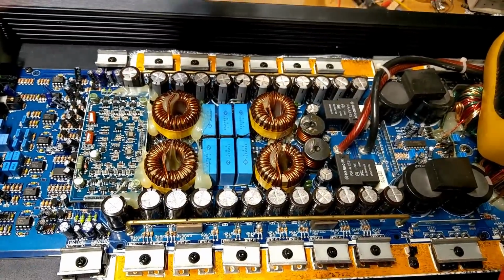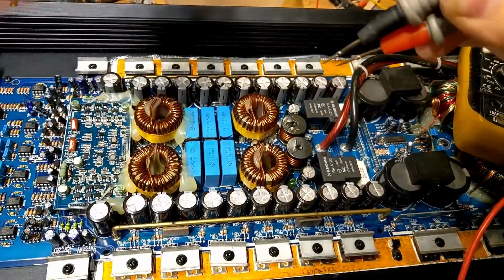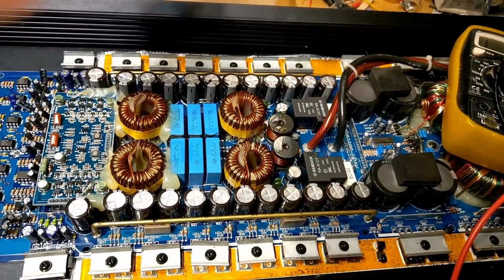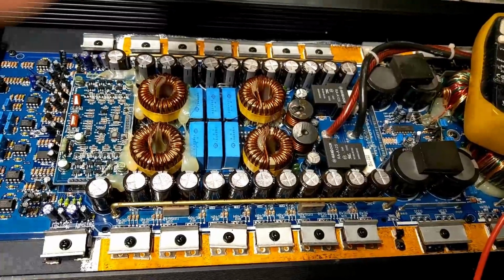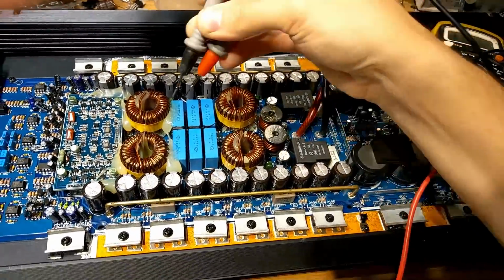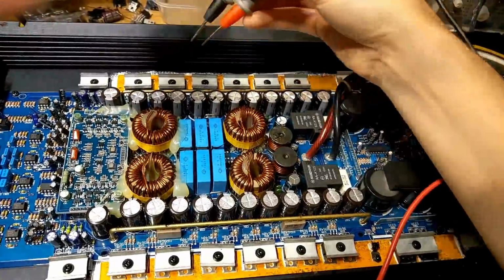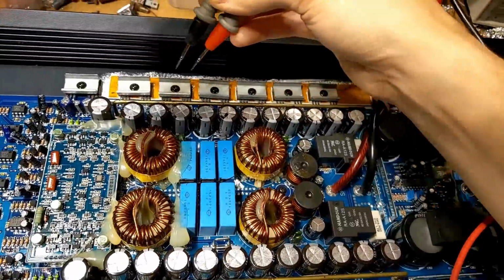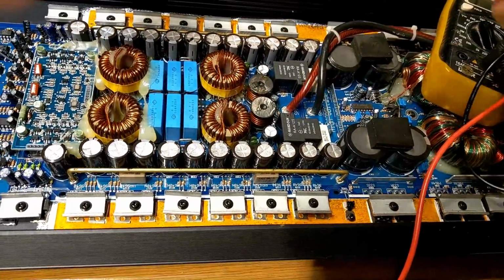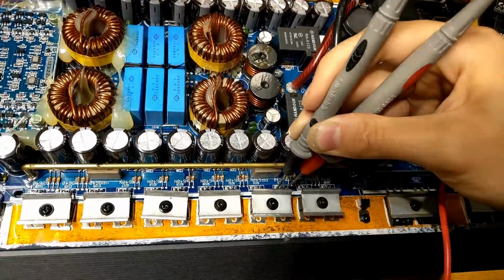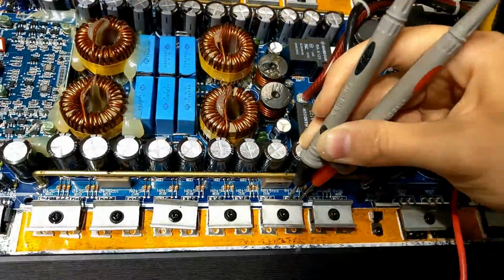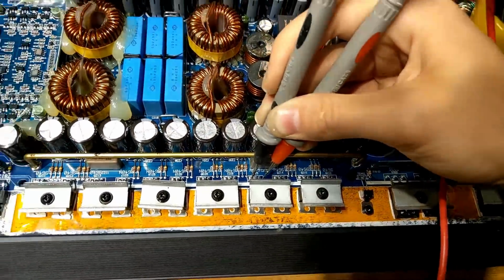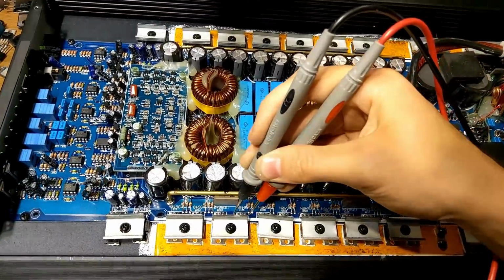So this amplifier actually has 4 separate little amplifiers inside that all combine, they all parallel after the filter section to drive a 1 ohm or 0.5 ohm load in this case. So we've got 1, 2, 3, 4 inductors, and each little quarter has 9640 and 640N MOSFETs. That's P channel and N channel FETs. The reason this amplifier has failed is because one of these little quarters of the amplifier has died. So we have shorted MOSFETs, both 9640 and 640N, on this little fourth of the amplifier. The other ones are all okay.